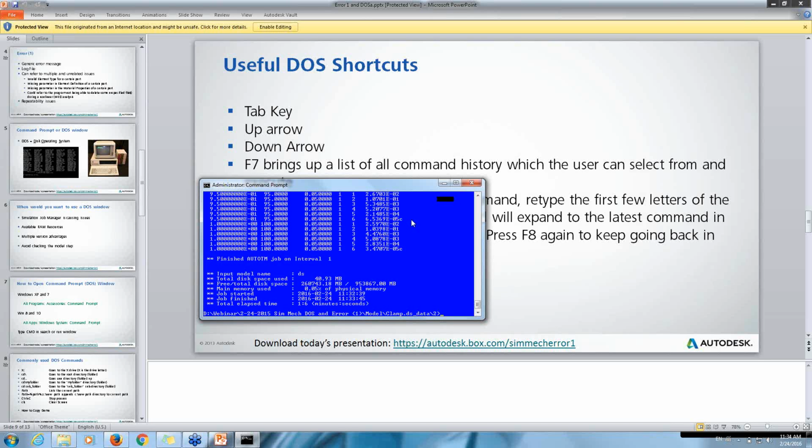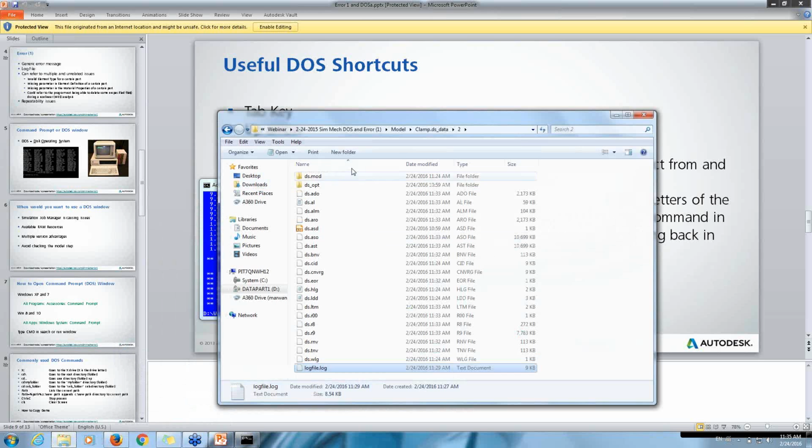So that becomes a little bit more tricky to modify things or loads that are in the FEM files. If you want to modify, let's say, a material property, that's going to be in the FEM file, right? Or let's say the gravitational force, it's going to be in the FEM file, I think. If you want to modify something like a nodal force, that is not in the FEM file. A nodal force would be, let me show you, in the .mod folder.